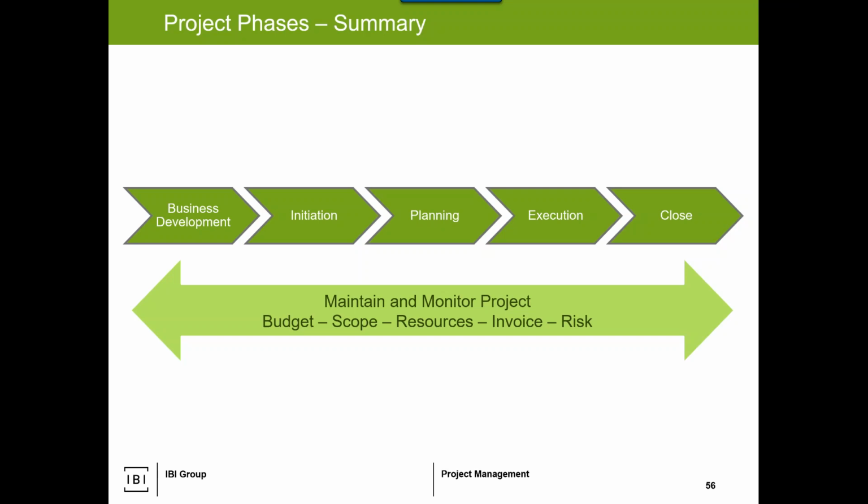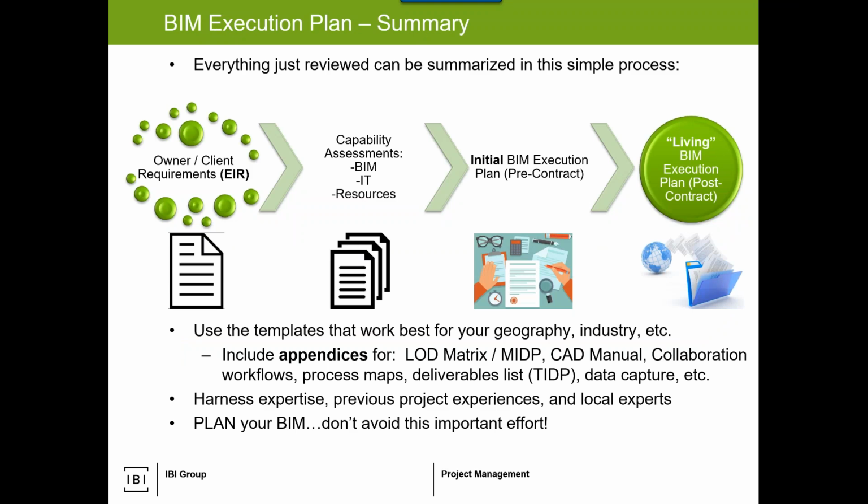Infuse it back to the world of the BIM coordinator to understand how we're executing a project, why, owner's requirements, our assessments, plan the execution plan, augment that execution plan to reflect potential changes in scope or changes in approaches, changes in workflow, workflow use diagrams, etc. Know what we're modeling, LOD matrix, who's modeling what and when, and how developed it will be at the different phases of the project, schematic or 30, 60, 90, so the design phase, in construction, into operations.